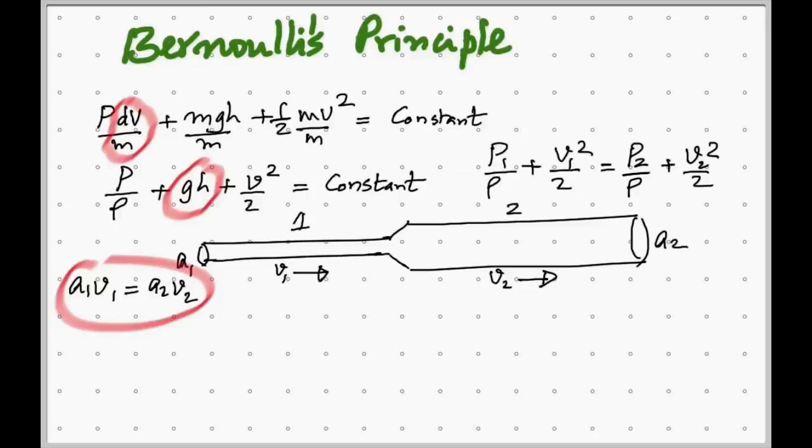But now to go to where the pressure is bigger or smaller, you have to use Bernoulli's principle. So take a look at it and then answer. We already found that V1 is greater than V2, didn't we? Okay. If V1 is greater than V2, P1 is surely less than P2. So where the velocity is higher, the pressure is lower. That is Bernoulli's principle.